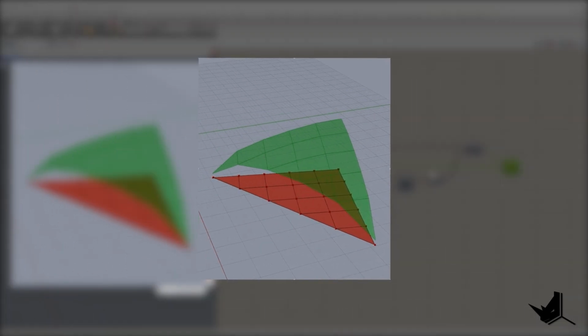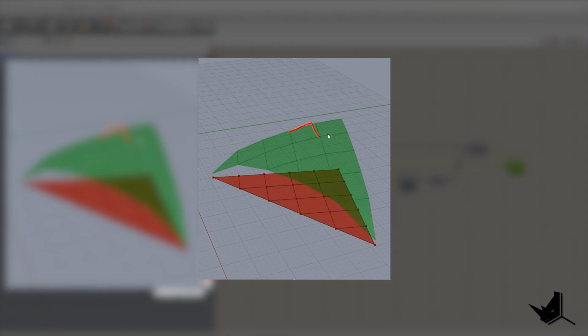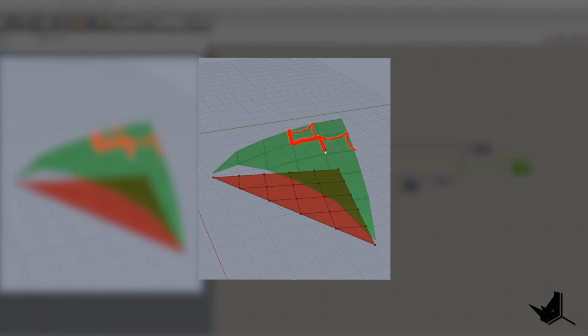Later on we'll use the same items, and let's say for this element, these 2 segments are closer to the attractor curve, and for these 2 we'll create a catenary curve, and from these 2 we'll create straight lines. Also here as well, straight lines, catenary curve, also here catenary curve, straight lines, here as well. And using that logic we'll create our final roof design.